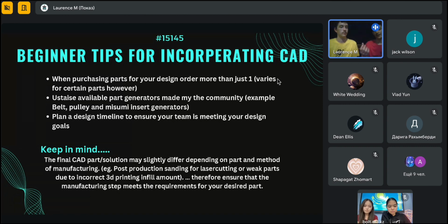At our regional event, our first competition, one of our square beams at the back, our inner side plate, completely snapped off, so we had no support there. If a robot were to come to our corner, it would have broken. So if you laser cut extra plates, that sort of thing will be very helpful and it will pay off.